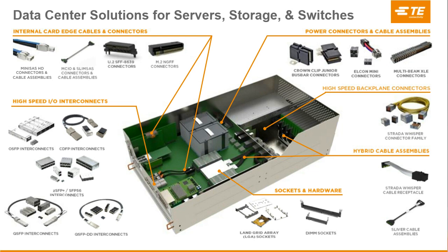But there's a 24x difference between the thermal conductivity of air and water, and so it's a natural progression that as these power loads move from a few hundred milliwatts per square centimeter to north of a watt per square centimeter, there will be a transition, and that just maps back to the overall rack increases in power per square meter.